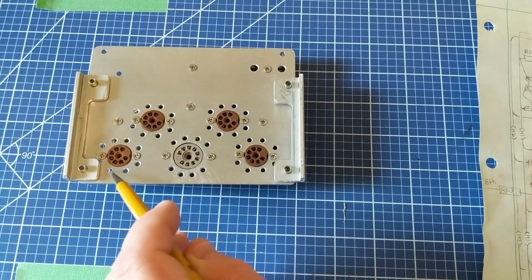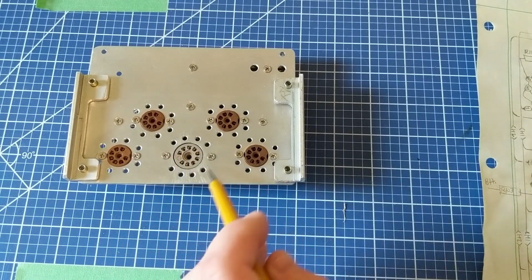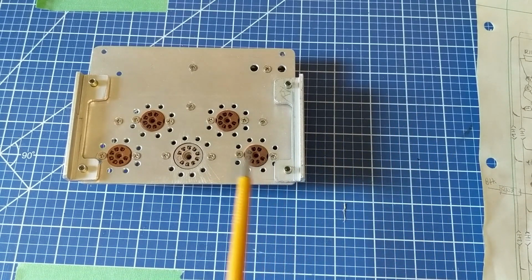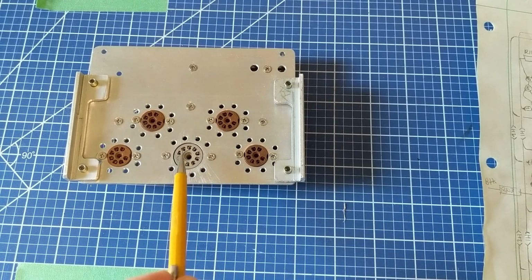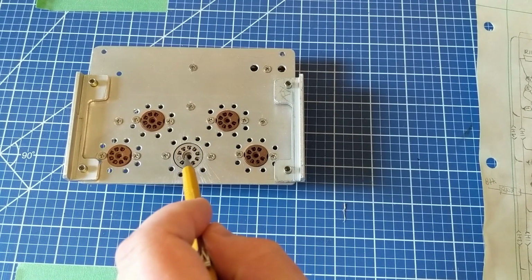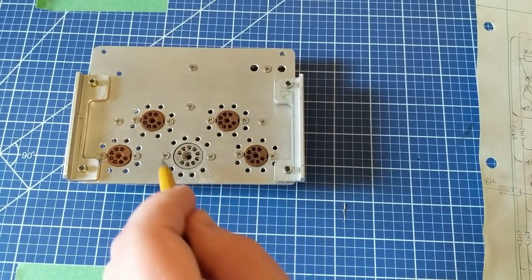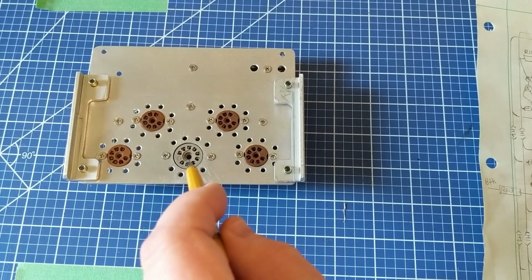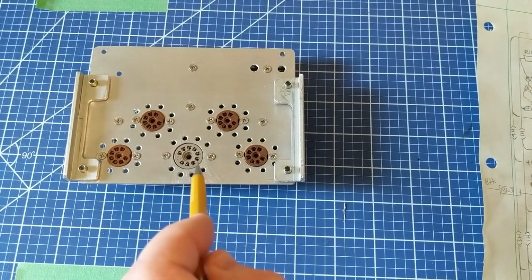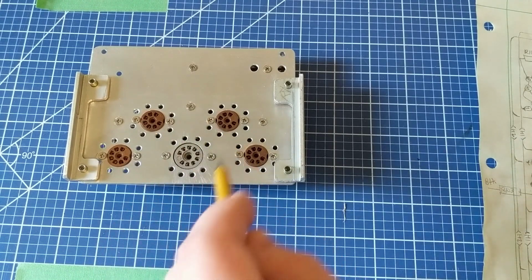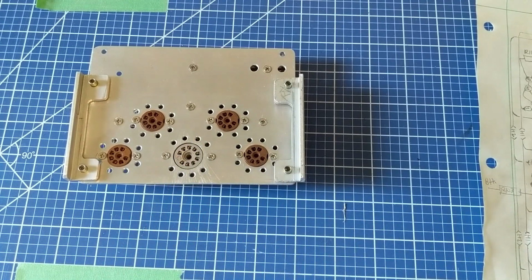The holes surrounding each of the sockets are designed for a couple of purposes. The first one is for airflow. It allows air to come up between the tube and the top plate of the chassis. There's going to be a larger hole in the chassis, larger than the diameter of the tube, that allows airflow to come up between the outside of the tube wall and the outer circle describing the hole in the upper chassis.